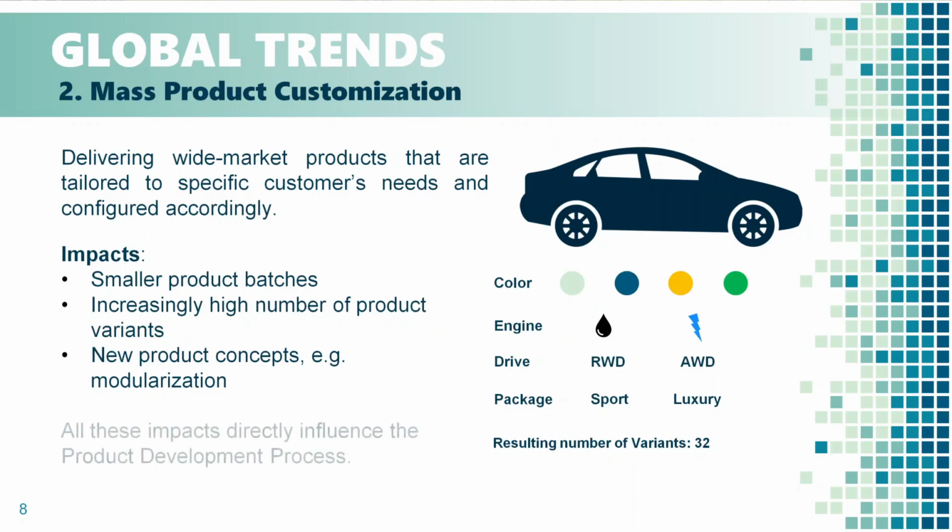So, what does that mean for a product designer? It means we have to make decisions regarding which components are subject to customization early on in the development process. We need to divide our products in standalone modules and features that can be easily exchanged, and we need to keep the variance cost in mind.